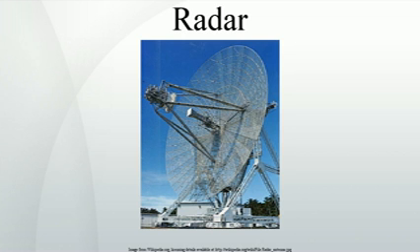Knowing the shape of the desired received signal, a pulse, an optimal receiver can be designed using a matched filter, a display processor to produce signals for human-readable output devices, an electronic section that controls all those devices and the antenna to perform the radar scan ordered by software, a link to end-user devices and displays.